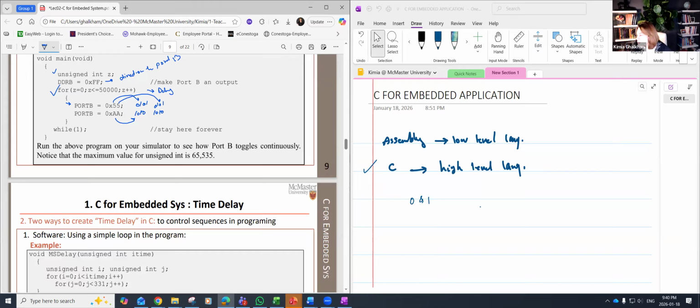For this purpose, simply define a variable, start it from 0, and just set a maximum in order to loop. Now, if we define the delay to a certain range of time, for example, 1000 milliseconds, in here I have 50,000 and say that is 1000 milliseconds. It might not be functional for a higher speed microcontroller, since different compilers produce different assembly code that results in different time delay. If we want to use it in different devices, we will discuss this in more detail in another lecture, but